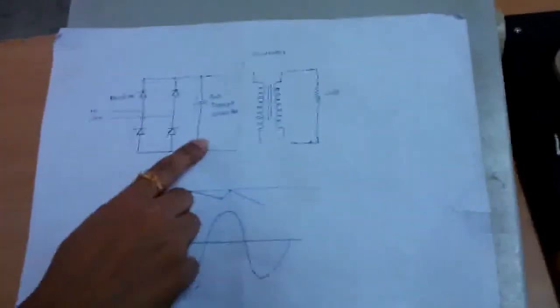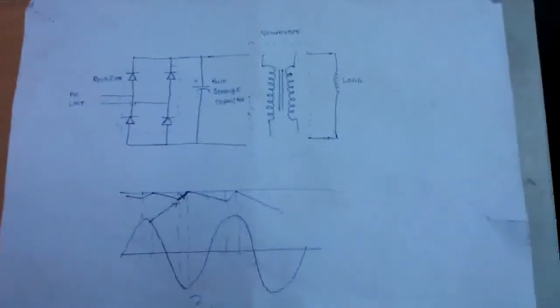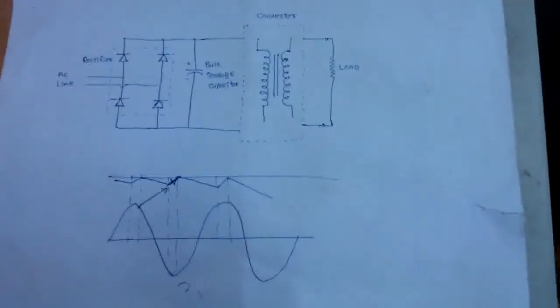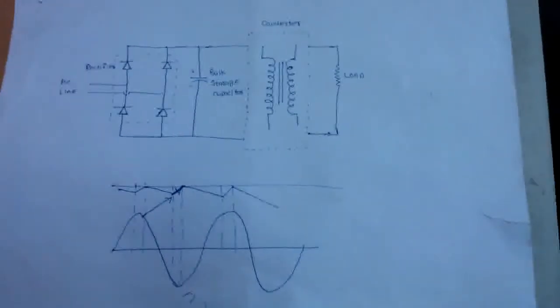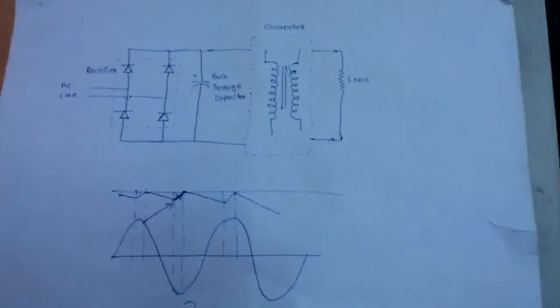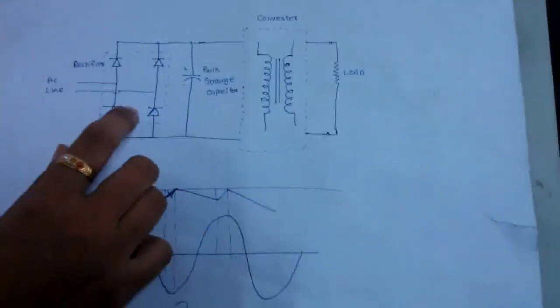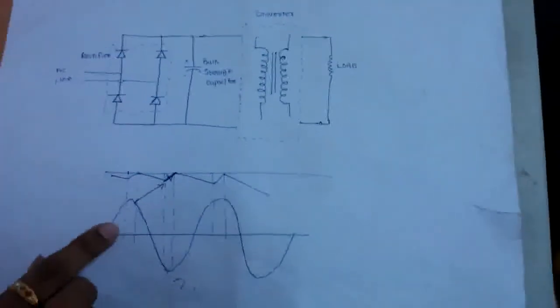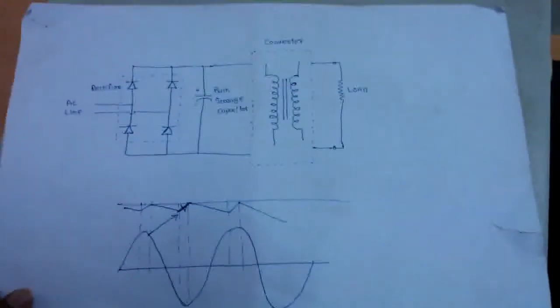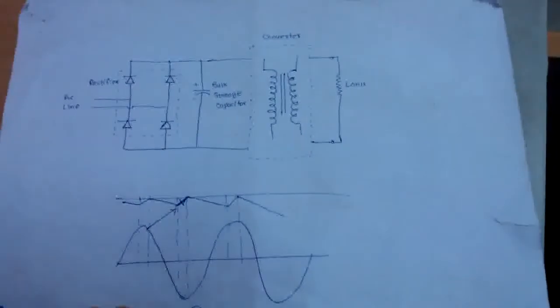Most offline appliances use a bridge rectifier associated with a bulk capacitor to draw DC voltage from the AC supply. This technique results in high harmonic content, which will reduce the power factor. In effect, a simple rectification technique draws power from the mains only when the instantaneous AC voltage exceeds the capacitor voltage. This occurs near line voltage peak and results in a high charge current spike. Consequently, a poor power factor in the range of 0.5 to 0.7 is generated.